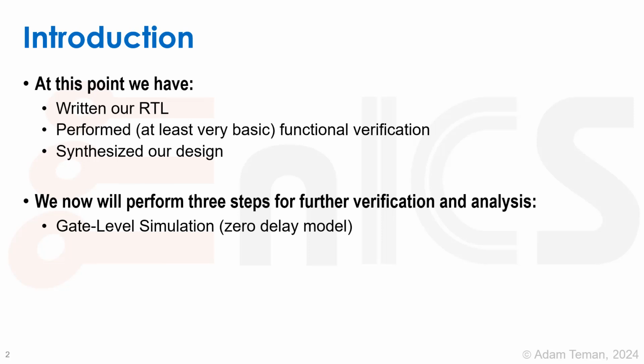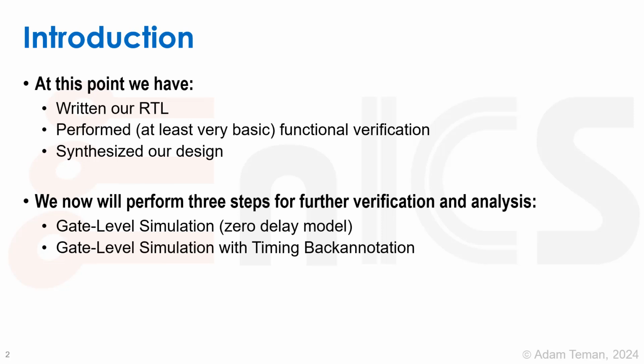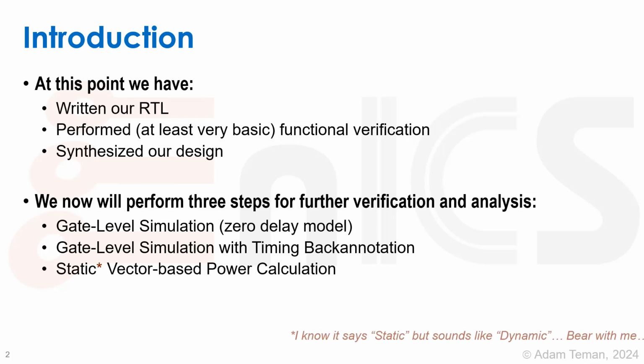First, we're going to perform gate level simulation with a zero delay model. So we're going to run a gate level simulation on our netlist and make sure that it still works after running synthesis. Then we're going to back annotate our timing from our synthesized design, so we actually have real delays and so forth. We're going to stick them back into the simulation and see that, again, we don't have any type of timing violations and things still work. Finally, we're going to run static vector-based power calculation. And I know that I said static and it sounds like dynamic because it's vector-based, but bear with me, I will touch on that later.